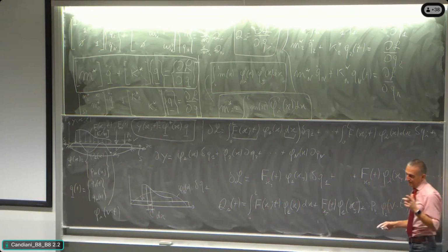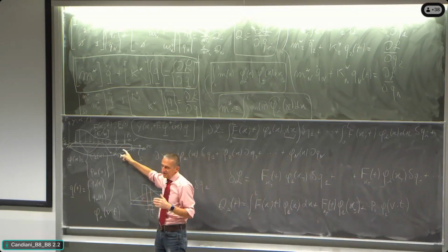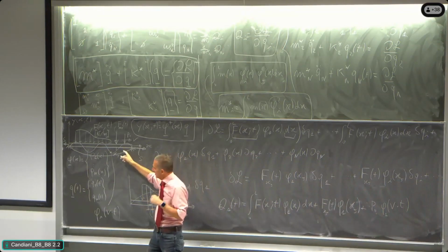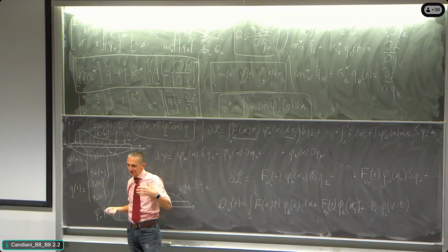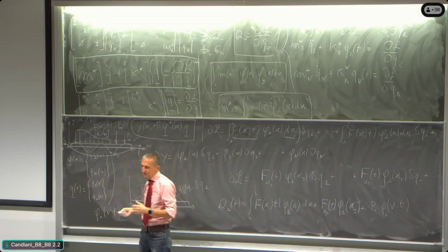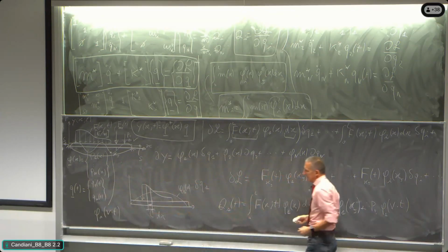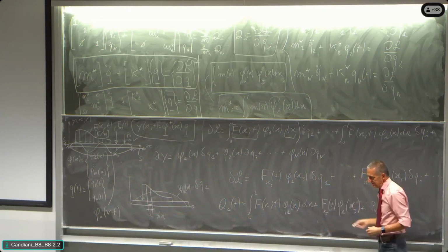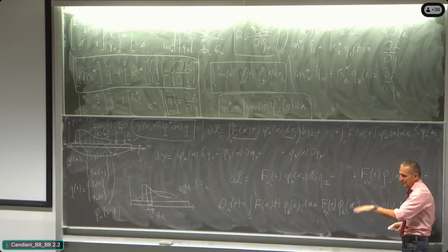Actually, what is happening is that we are transforming into the time domain the space domain oscillation of the modal shape. And so we are understanding that the vehicle that is running at constant velocity over the bridge is actually exciting dynamically the structure. And if we have several vehicles that are moving this way, very correlated, the modes are rising up, unless there is something actually bumping with that frequency over the deck.